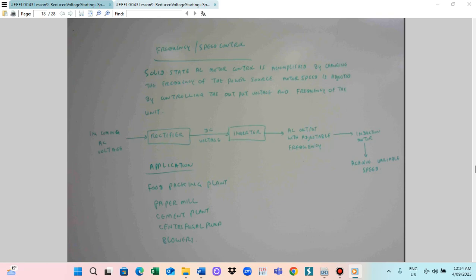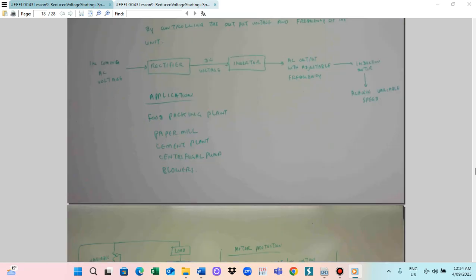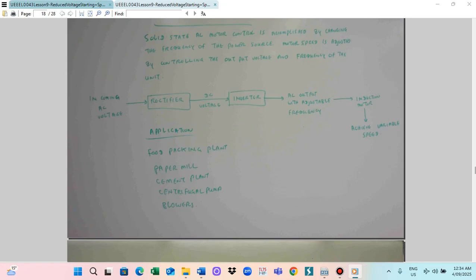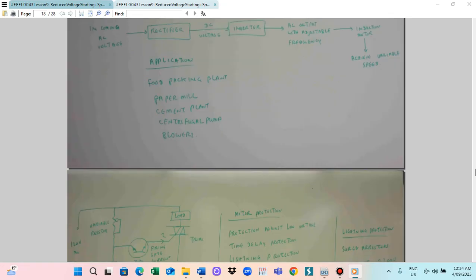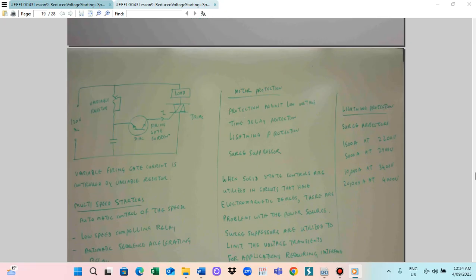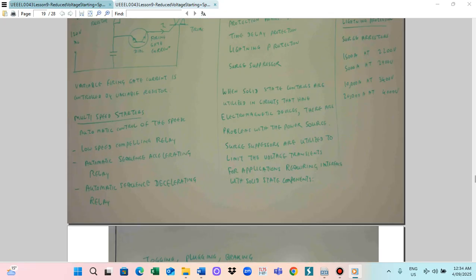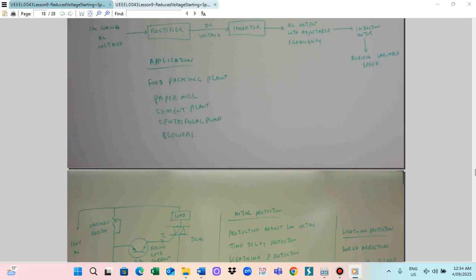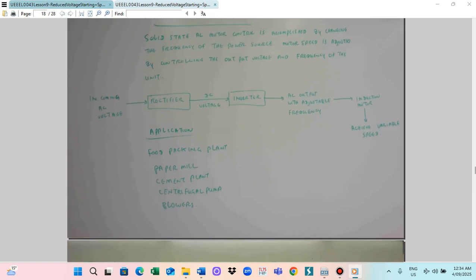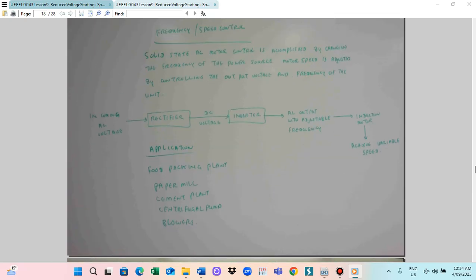This is how we can control the speed of the AC motor, by the circuit. When you use this, we use low speed first, starting at the low speed and then switching to the higher speed. Also the automatic sequence is controlled by a relay. Sometimes the starting and the running time is performed by the sequencer. The sequencer is also included in the motor starter.